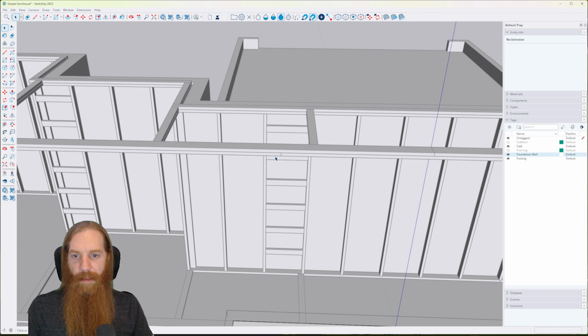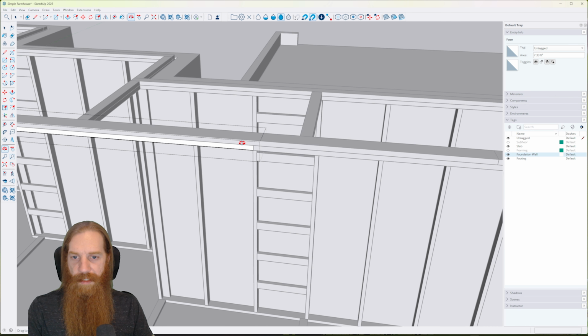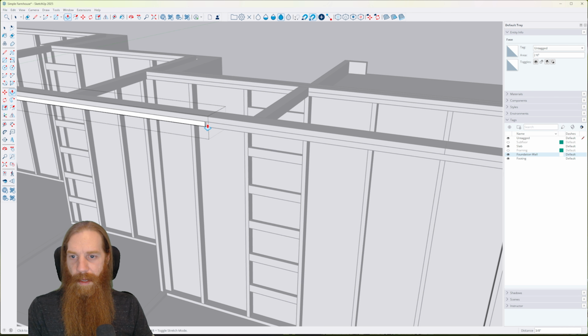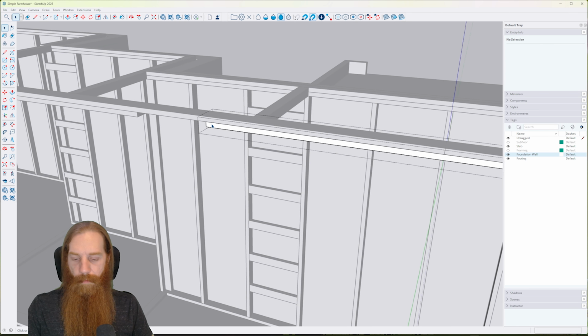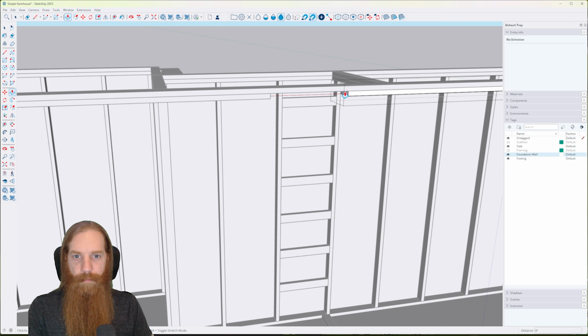Now that seam kind of lands right in the middle. It's still not going to be 4 feet away from the seams on the second top plate, but that's not the worst thing in the world. So 24 inches over, and then we're going to bring this all the way to there. Okay, that was a lot of work just to figure out these plates.